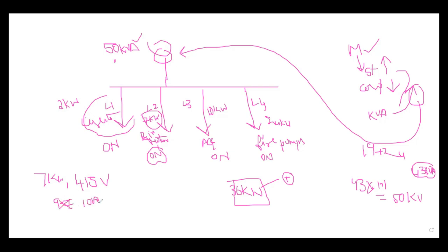But in my manufacturer catalog, it was said that when you are turning on the motor, the starting current of the motor is 6 times, and the power factor is 0.3 only. Then 60 amps at 0.3 power factor, and the voltage level is 415 volts, then what is the power required? 1.732 into 0.415 into 60 amps into 0.3 gives you 13 kilowatt.